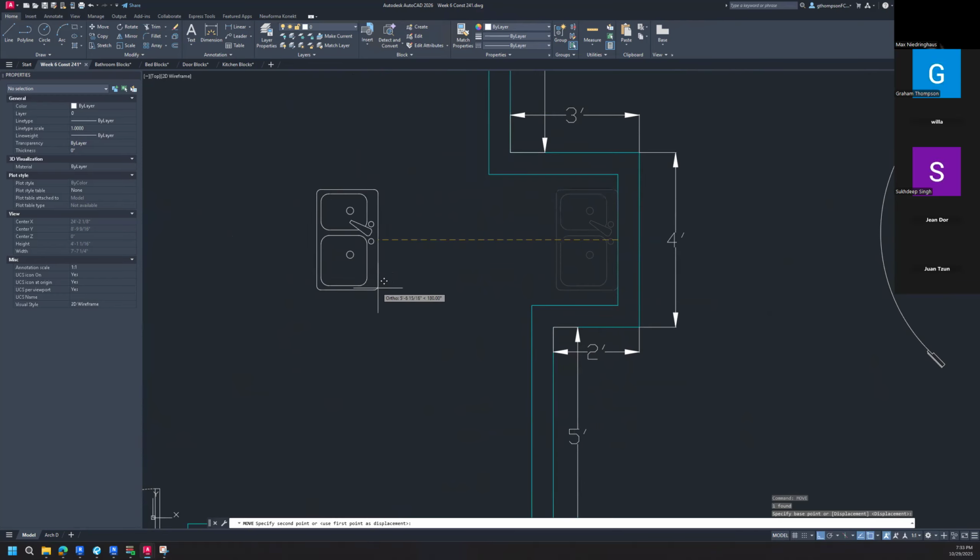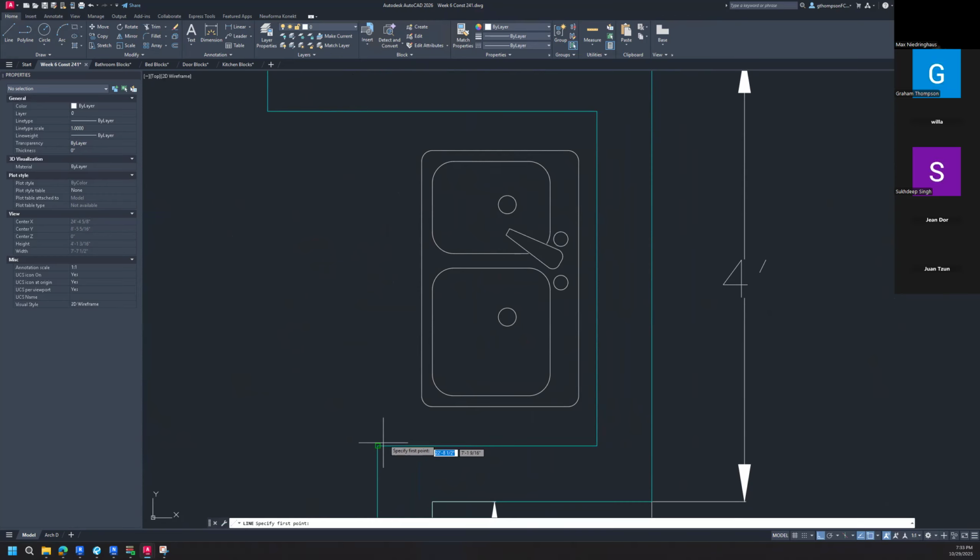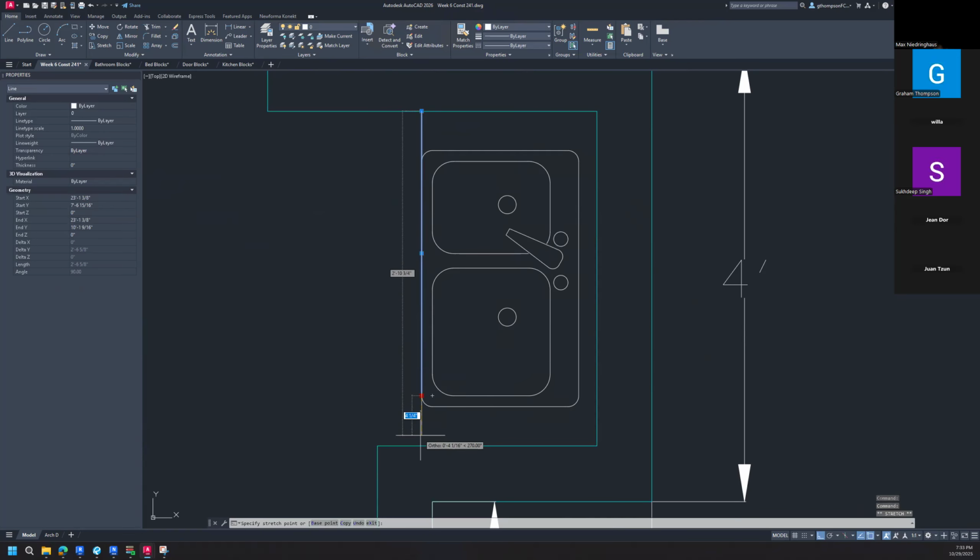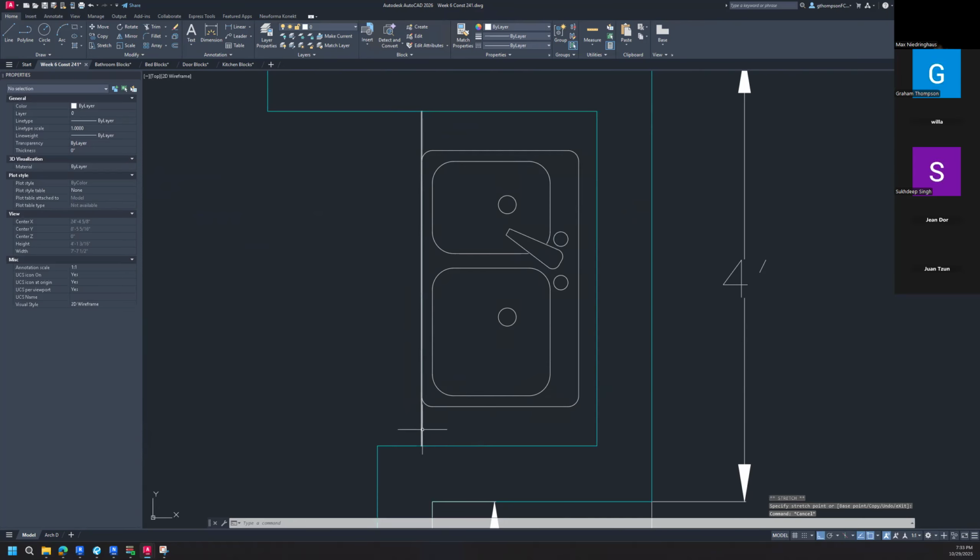And I just want to go ahead and draw in, maybe I want to draw on a line here, give it a 2-inch. Right, I'll take that line, extend it down to here. And then knowing where I'm at, let's go ahead and give it, because I want it to be kind of symmetrical in the hole. I'm going to put a 1/2 inch backsplash on this. So I'm going to move this 1.5 inches. So I'll move it straight over 1.5 inches.